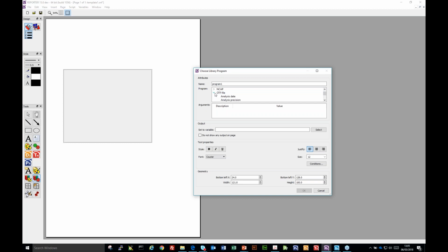So we can look at scripts that run on the OTF file or the results message files to produce information about the mass information in your model, or the termination status, so that you can automatically pull out information about how the analysis has performed.